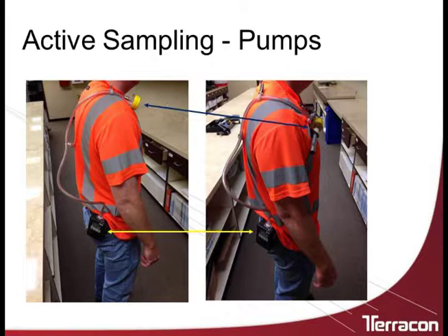What the cyclone does is it goes after the respirable fraction of that dust. So anything that is 10 microns and less would be collected on the filter. The rest of it would fall out in the bottom of this little cyclone. That's similar to a cyclone you would see for a local exhaust system, a control measure on the local exhaust, only on a smaller scale.